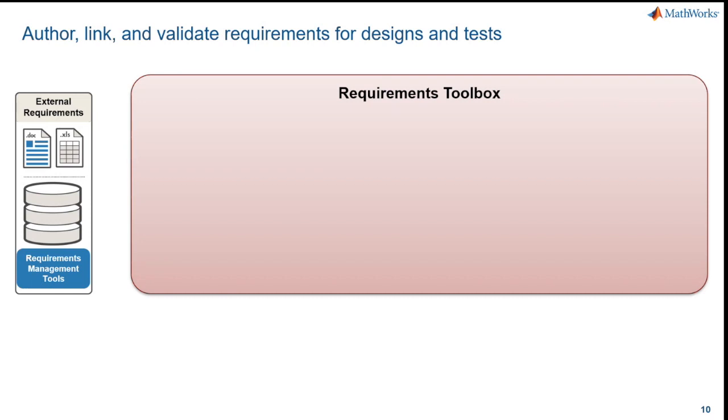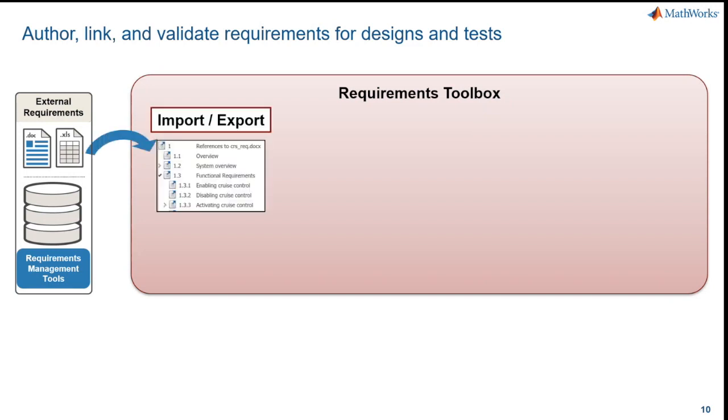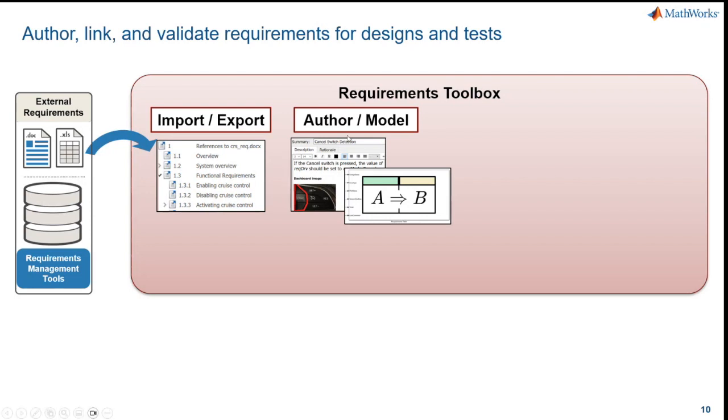If you are using requirements in another tool, then there are import operations for Word, Excel, DOORS, and support for the standard requirements interchange format, ReqIF. We talk about it after that. You can also author requirements where the source of requirements is in Simulink, such as the requirements table.